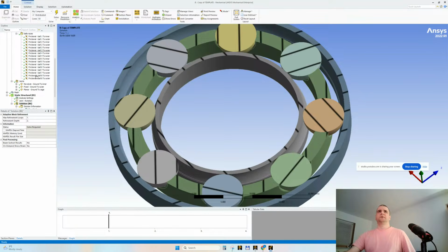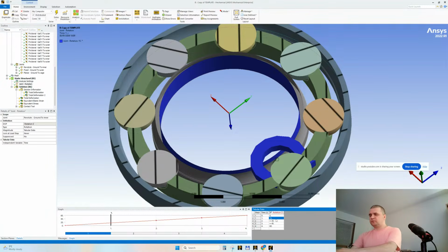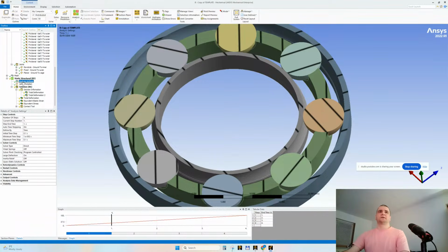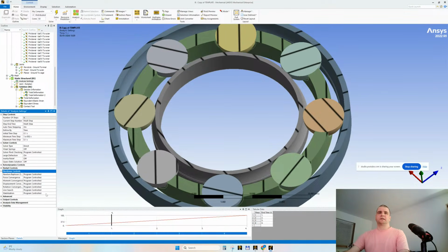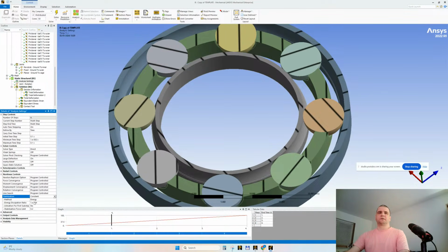Why doesn't it work? Why doesn't it work? Let's force something, you know? Let's go again to 25 and 100. And let's force a convergence. How do we force convergence? Look here. I select all the steps, nonlinear controls, and stabilization. Save and solve.